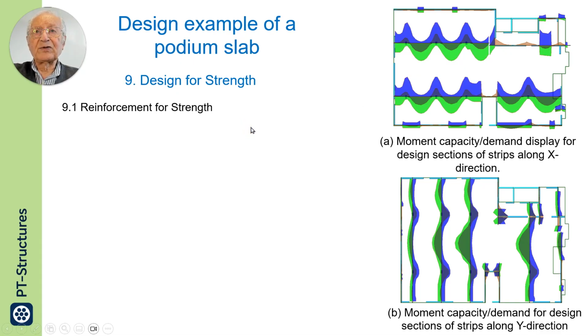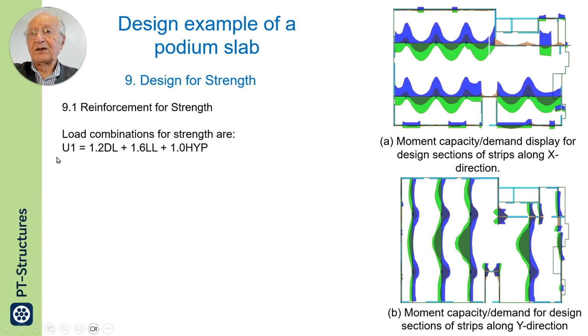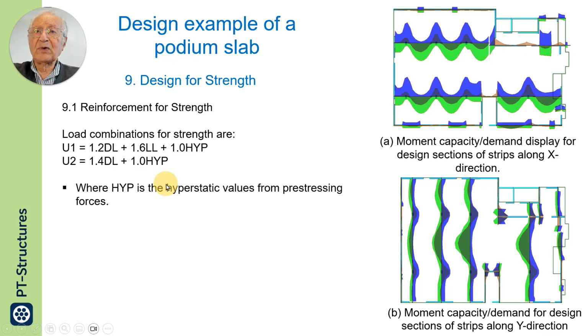Here I have used a computer software. We add rebar where the demand is not met. There are load combinations in the code. This is the primary load combination. There is another load combination requirement that rarely governs. The one above is mostly the governing.